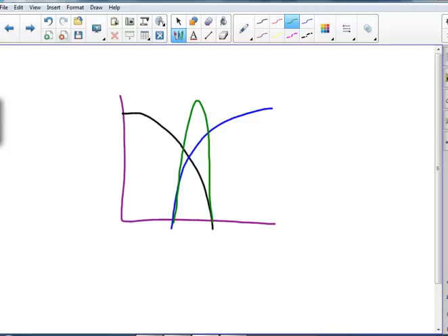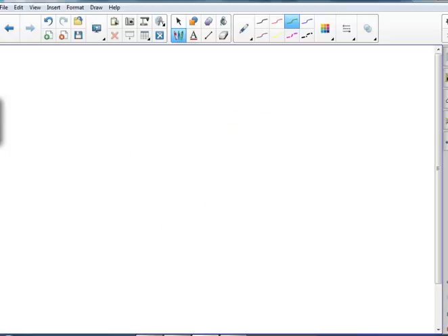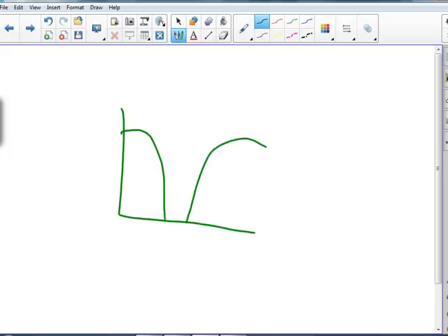So instead of doing that, it's got something that looks like this and something that looks like that, and it's passing both of them. But whoever's in the middle, we're rejecting it. So someone's out there trying to jam my radio. One of the second-year students who built the AM transmitter is out there trying to jam 1290 KCAR, and I can't get it. And along with a lot of other things, because it's jamming a lot of stuff. And so I make a band reject filter to get rid of the jamming going on.